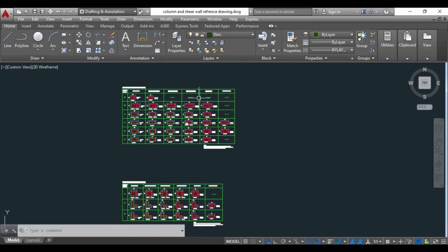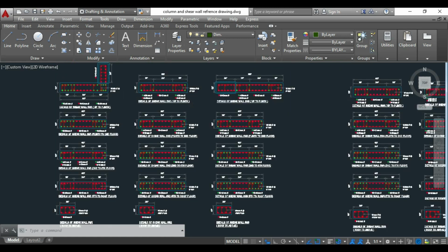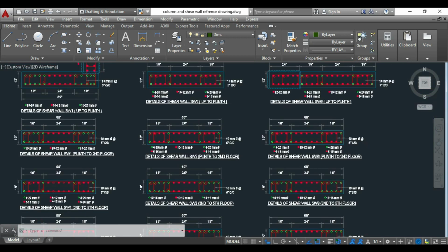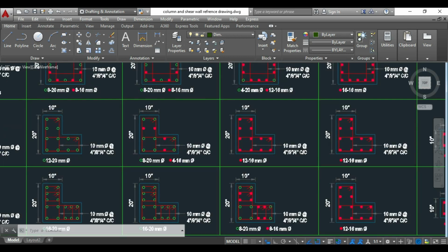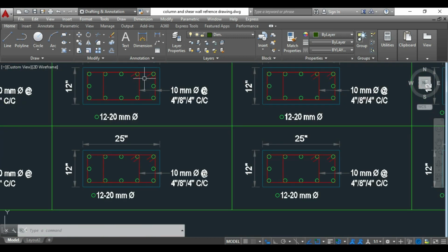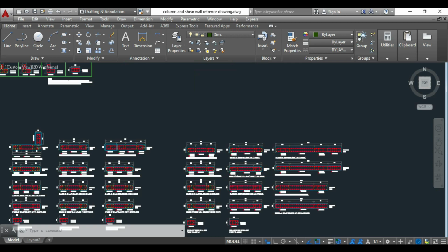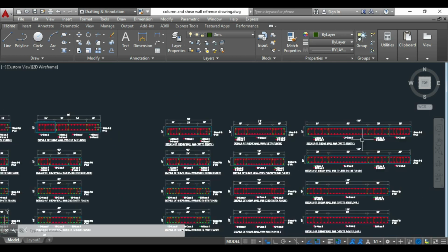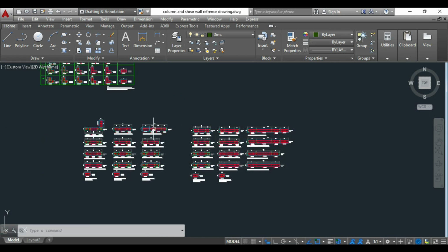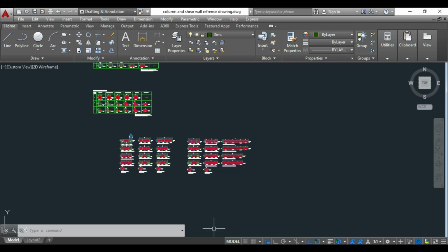All right. So once that is done, there is the data for shear wall also, 0.3L. Okay, shear wall and column have almost a similar type of design process, not design, detailing process. So I'll be giving you a walkthrough even on this. 0.3 times L, if you take it, you'll be able to get the area of steel, and here you provide the minimum amount of steel. So even this I'll provide to you, and I'll show you how you can manipulate them easily. Just copy, cut, paste commands are there. You can use that and you can do it. So you don't have to do anything from scratch. Okay. So this also I'll provide to you.